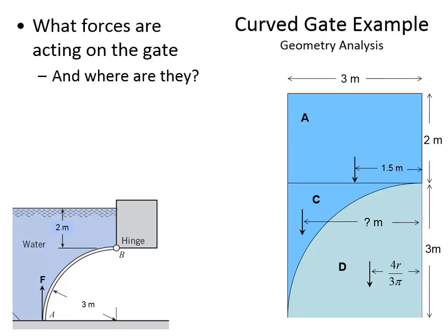So the moment analysis that we can do for that is that we have a force opening, and what moment distance is it for the opening? What's the relevant length parameter that we should use from the hinge to the opening force? 3 meters, good.